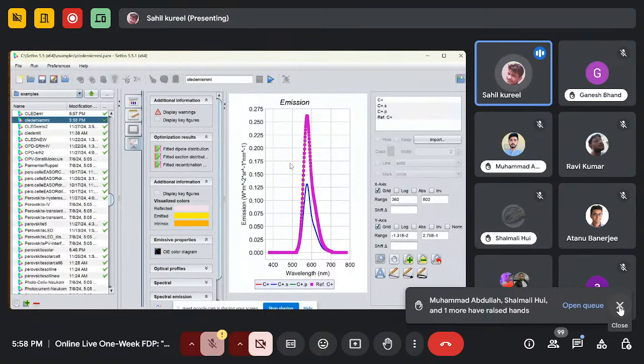You can see here the results of the fit emissions. It is the resulting emission spectrum for the emission plot. Next, it lists these spectral data as the fitting target to reconstruct the dipole distributions. Firstly, here we calculated an artificial emission spectrum and then SETFOS reconstructs the dipole distributions. So you can fit your own data and get a more accurate result.